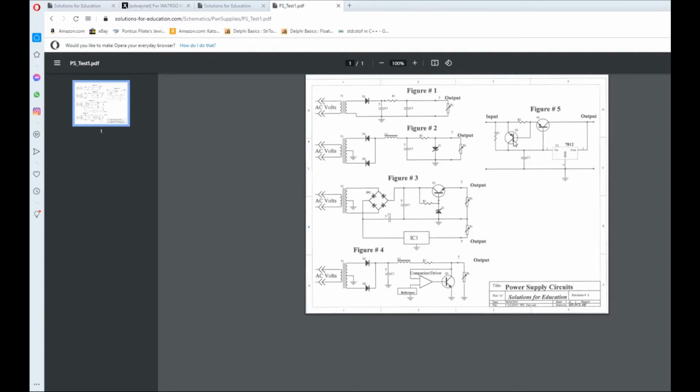Now let's go up here. This is really an interesting circuit. Here is your 7812 that I described before. This 7812 does a really good job, and it draws current through this resistor here and on out to the output, and it does a fantastic job. Like I said, this guy has about 27 transistors inside here, along with resistors, diodes, and everything else. But he's only good for about 750 milliamps. Since he's only good for about 750 milliamps, what happens if you get up there in the, say, 600, 700 milliamp range?